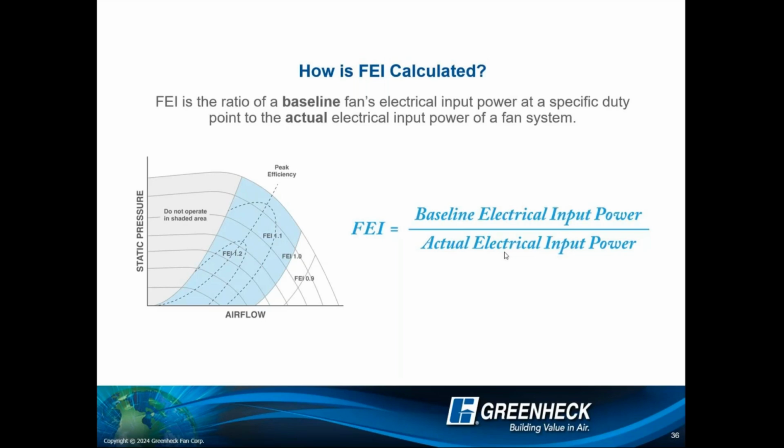So as a manufacturer provides this information to you, you can confirm, yes, I made a good selection on which fan it is, which size it is at this operating point. Now, I'm not saying you shouldn't look at the fan curve and make sure you're not in a bad place, or look at the min max curve and know where I'm at in my range of operation. Those are two variables that are important. This is just a third variable confirming that this is the right fan for you.